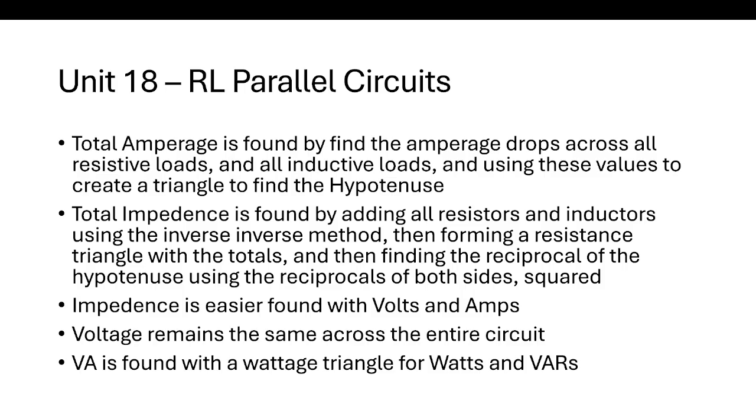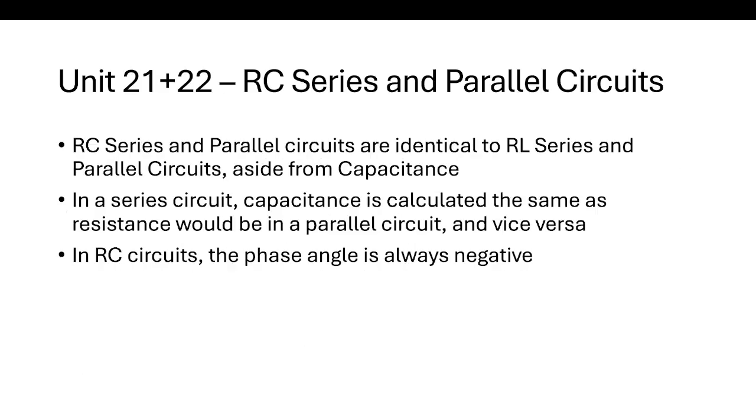It's not as easy compared to just doing the Ohm's law formula, which as soon as you find your voltage and amperage, voltage and wattage, amperage and wattage, any of that, you can find your impedance all the same. Your voltage remains the same across the entire circuit, and your VA is found with your wattage triangle with watts and VARs. Pretty simple.